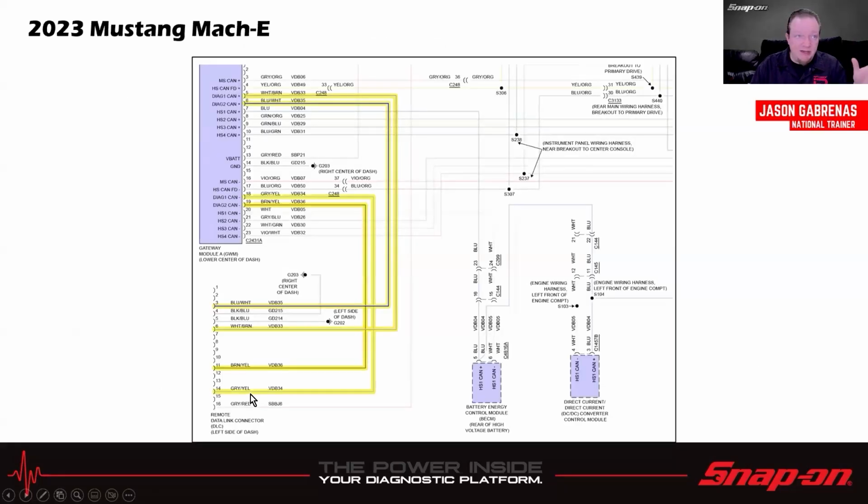So don't need to get all the way into that. I'm not an electronics engineer by any means. I know just enough to be dangerous, I guess. As an example on a 2023 Mach-E, so as you see from the diagnostic connector, it's a diagnostic CAN, so it's still regular CAN. But then I see up here I have high-speed CANFD, and I have high-speed CANFD right there. So it has CANFD internally inside the vehicle through the gateway module.